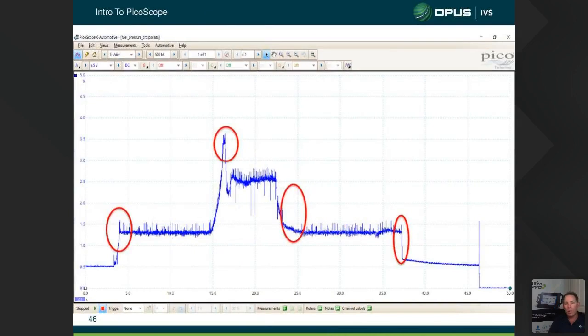Now, what happens straight away, the software presets to 5 volts there, and our time base is set at 5 seconds per division because this is a real-time test. And that's done automatically because we've selected that test from automotive. Now, the good thing is that fuel rail pressure test on a common rail diesel, it is the same for all rail pressure sensors. Exactly the same. The voltages are the same. What we should see here is exactly the same.